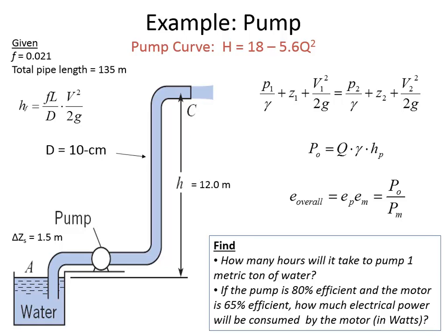But we haven't yet accounted for the efficiency. So we know that the efficiency is 0.52. So let me ask you, do we multiply by the efficiency or do we divide by the efficiency to find out how much electrical power is consumed? If this is the perfect case, if efficiency was 100%, it would take 2737 watts. So is it going to consume more electricity or less electricity than 2737 in reality? More. So we divide by our efficiency factor.